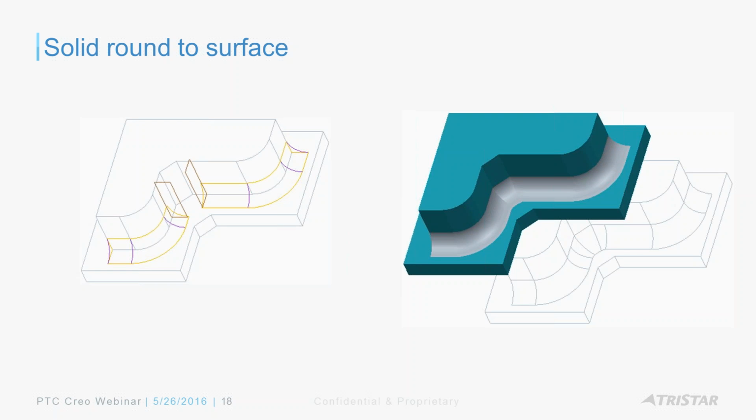Like I said many times, you may think your designs are not really organic shapes and they're regular models, but there are certain intricate regions in the model, like I said earlier, where your rounds simply fail. You're trying your best to work with Creo Parametric, and the system is so math driven, as you know, that it's simply unable to create a solid there. So it might be easier to convert your failing round into a surface round.